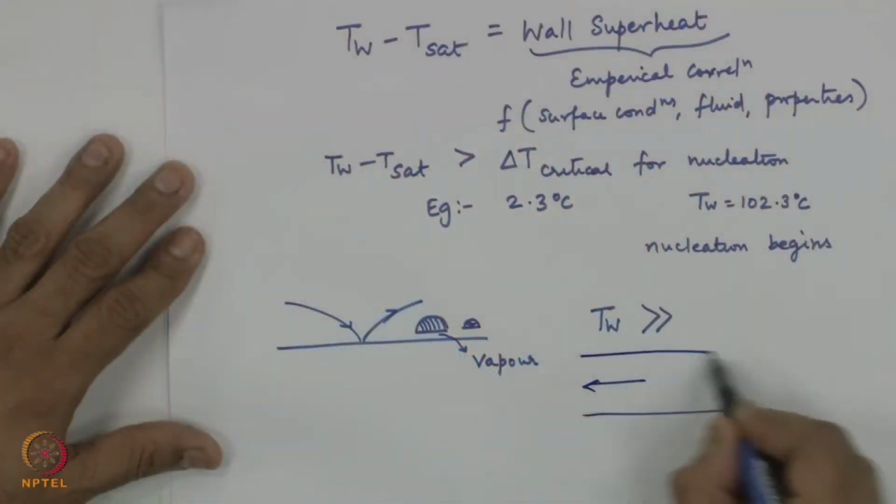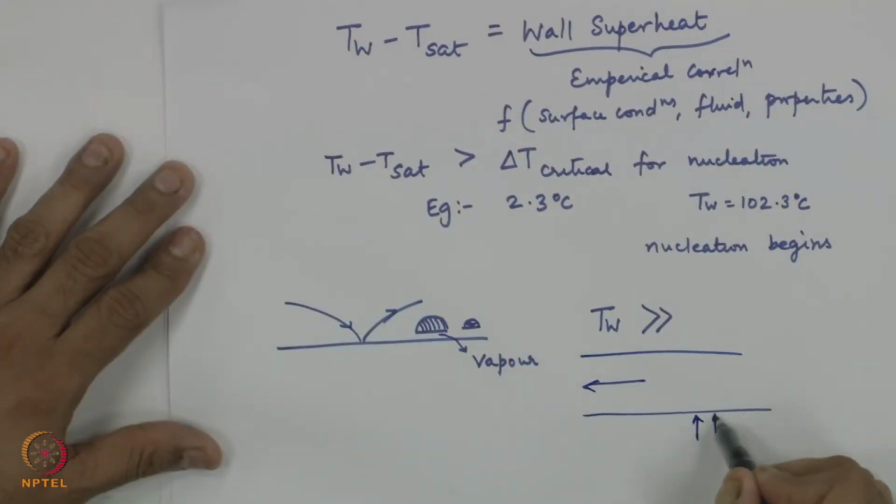the lack of contact between the liquid and the heated surface is very, very bad. That point where the liquid loses contact with the heated surface, because T wall becomes much greater than where liquid can establish contact, is very, very dangerous from the heat exchange point of view, from the engineering point of view. That point where the contact is lost should never be achieved, because suppose I have a tube and water is flowing through this, and there is a local hot spot. Local hot spot means there is some kind of flow maldistribution, and you come up to a surface where there is no flow in this path, and you are supplying heat.